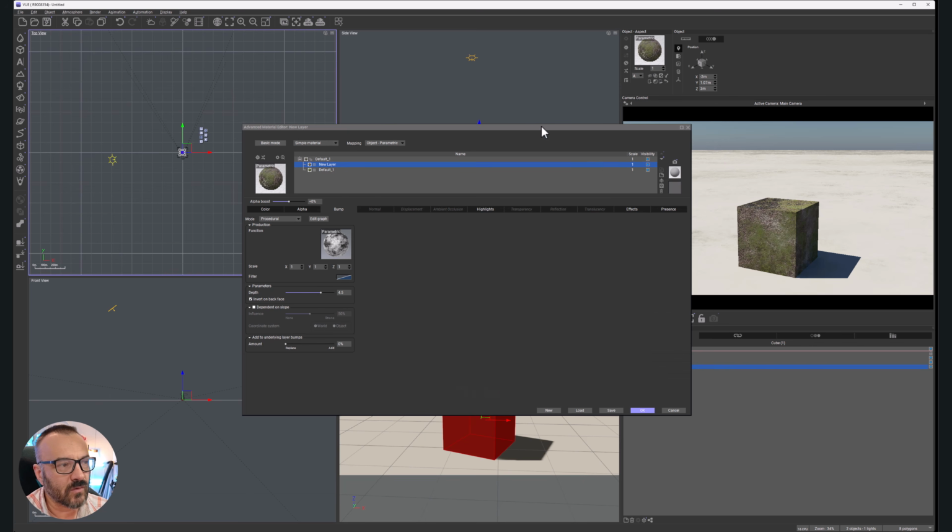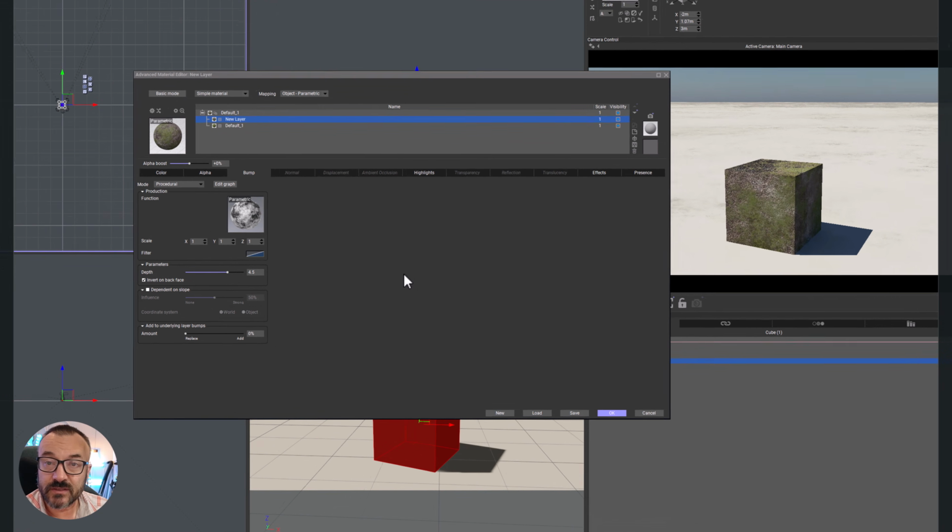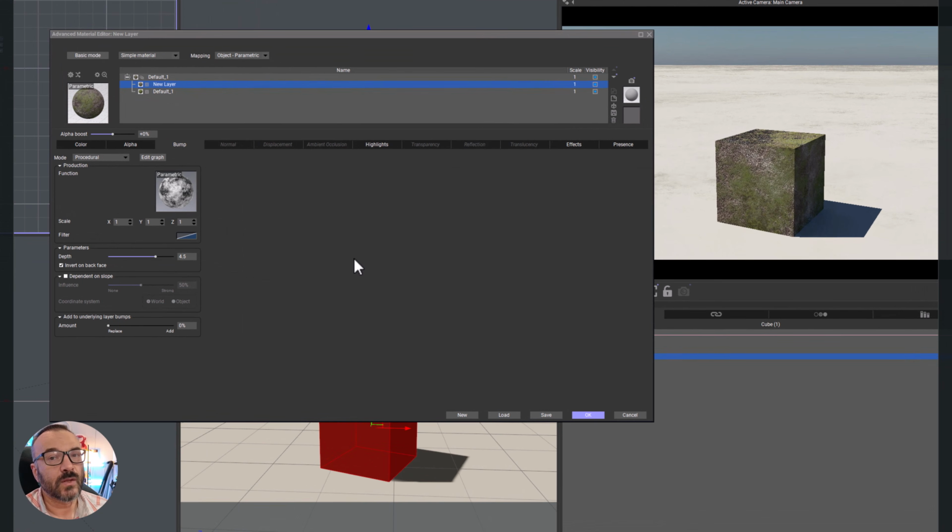Right here we have our switch. There you go. You'll notice sometimes bump maps are actually a very fast and nice way to create some shapes. And because it does not change the geometry, it takes much less time to calculate on our engine. I usually create a bump map to simulate far distance grass, and rocks work excellent. They almost don't take any computing time, and it looks very good.